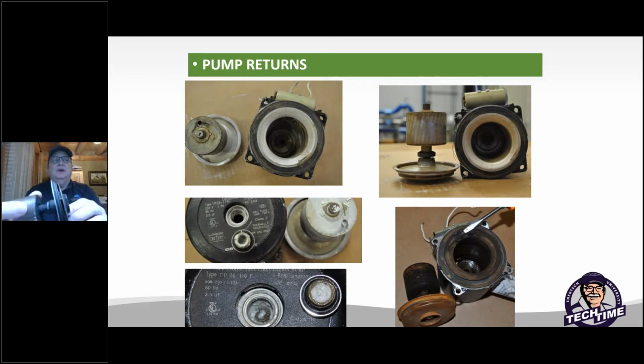And I also noticed that there's a lot of particles that go inside the impeller. And so obviously that creates bad turbulence, less performance, less water flow. So the importance of protecting and keeping your water clean and testing it is very important for the longevity of all the parts and less service calls. So bear with that, keep that in mind.